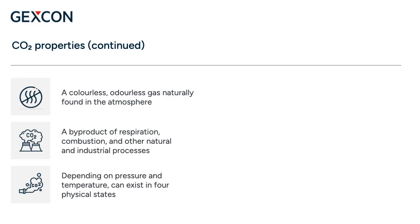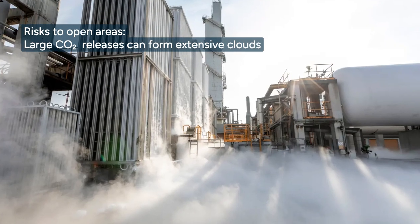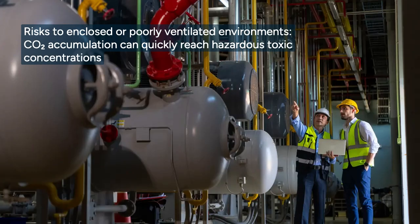What makes CO2 unique and also potentially hazardous is its density. It is 1.5 times heavier than air when released in its liquefied or supercritical form. This means CO2 behaves as a heavy gas, spreading close to the ground and accumulating in low-lying areas or confined spaces. This behavior poses significant risks in both open areas, where large releases can form extensive clouds, and enclosed or poorly ventilated environments where accumulation can quickly reach hazardous toxic concentrations.